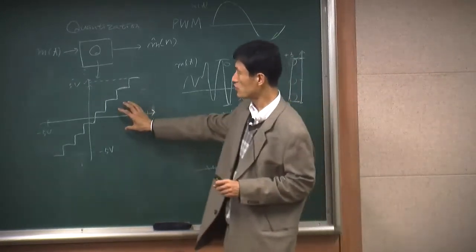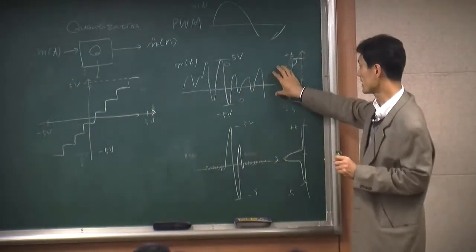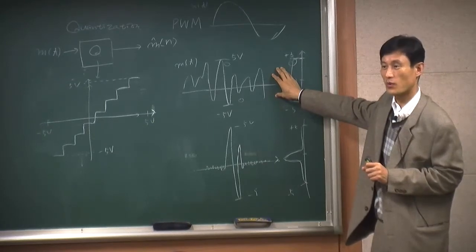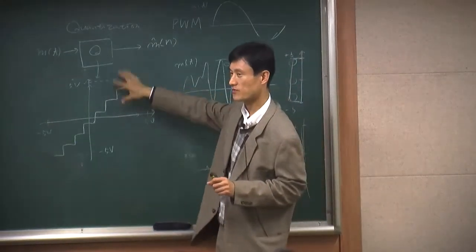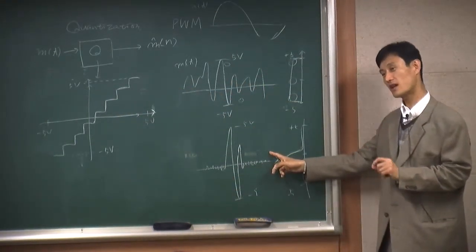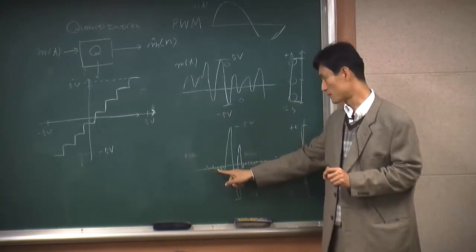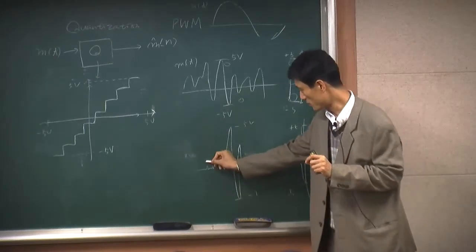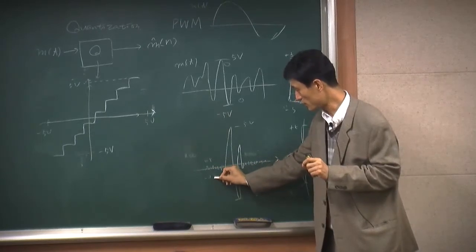So this kind of uniform quantizer works best in this kind of scenario, for this kind of signal. Why is that? Let's say we have this uniform quantizer, but our input looks like this. In that case, what happened? Most of the time you have very small signals, like 0.5, minus 0.2, something like that, right?